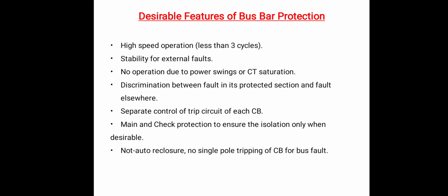Some experts are of the opinion that the local bus protection should not be provided and the bus faults cleared by the backup relays at the neighboring stations, as the provision of the local bus protection would certainly increase the risk of inadvertent tripping. So we will be most careful with this type of feature of bus bar protective devices.